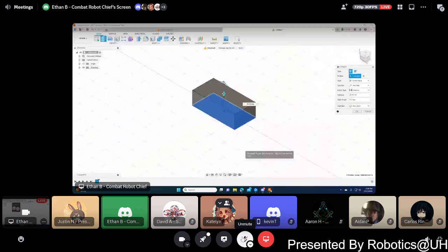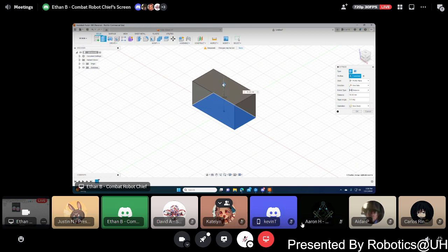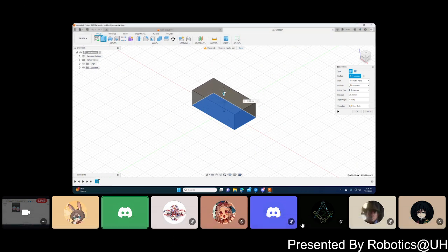Okay, that makes sense. So continuing on for extrudes, we can choose what dimension we get. In this case, it goes by multiples of 5 if we drag down this arrow. Or here we can put in the dimensions individually. For this, I am going to do 30. It automatically has the dimensions in millimeters.